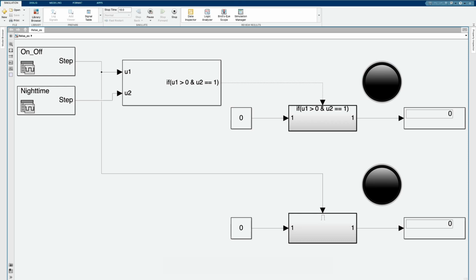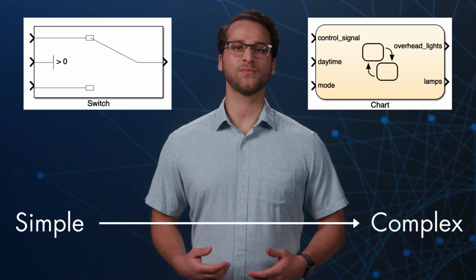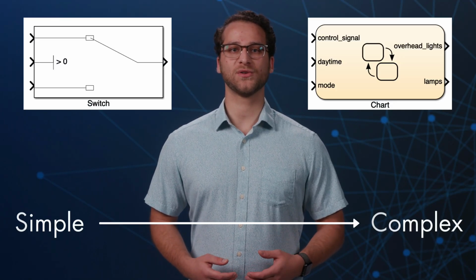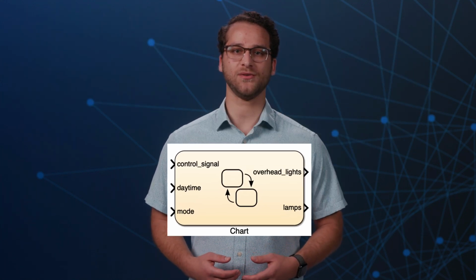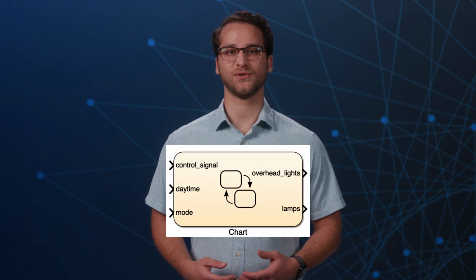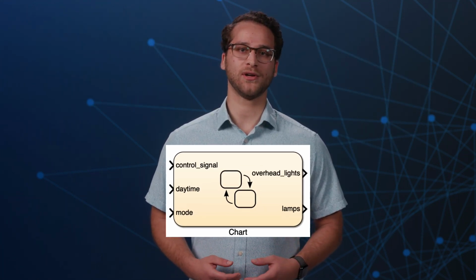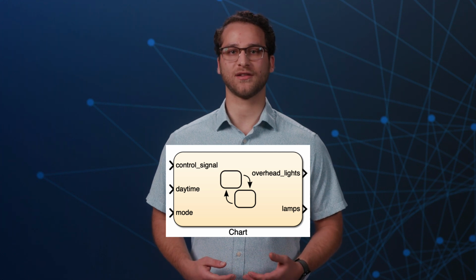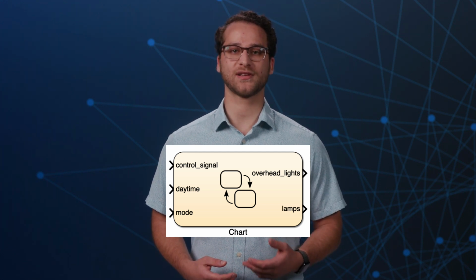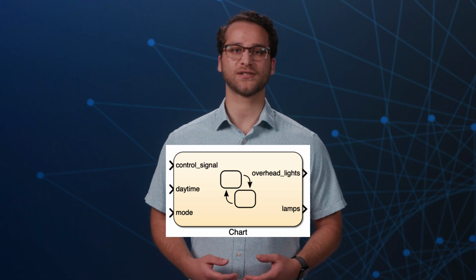This kind of logic can be defined with an if-else block, where the inputs contain multiple control signals that affect the output signals. For more complex conditional logic, where different modes of operation or states need to be used, Stateflow provides a simple solution. With Stateflow, you can describe the interconnected logic that determines different operating states of the system. Your states can become complex and nested, flexing the full logical capabilities of Stateflow.